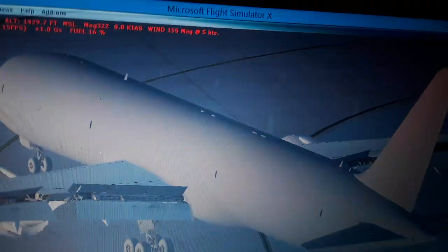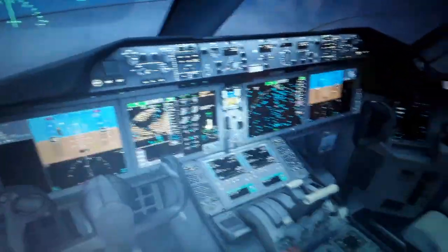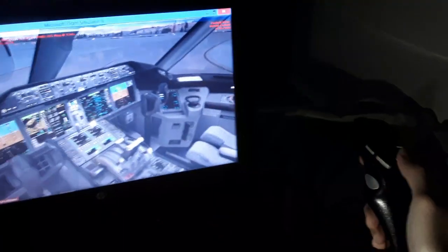So we have a few more things to see from the flight controls. I just talked to you about stabilizer trim. I have the stabilizer trim over here, this switch to control in flight the stabilizer trimming. So this Airbus side stick, I have the side stick priority button for the left and the right side, the push to talk, and the autopilot disengage switch for the Airbus.